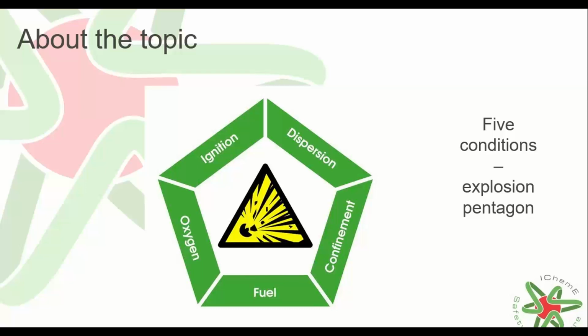And there are two broad categories of dust explosions, which are primary and secondary. And why is it important to discuss these two? Because a dust explosion initiated under conditions of confinement is called a primary dust explosion, and the force from that primary explosion may disturb surrounding dust, forming another dust cloud, and the flame from the primary explosion subsequently ignites the suspended dust cloud. And that's why secondary explosions are also initiated under conditions of confinement, and that's why generally more destructive than the primary explosion.